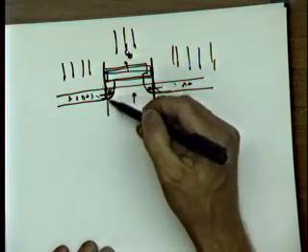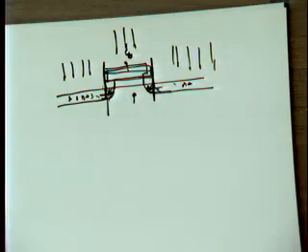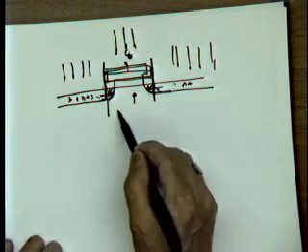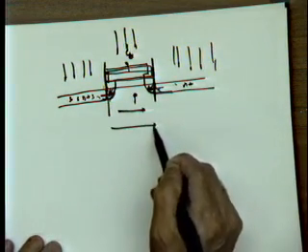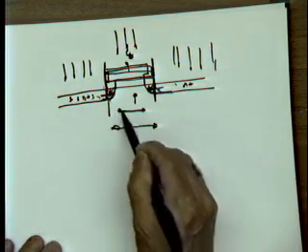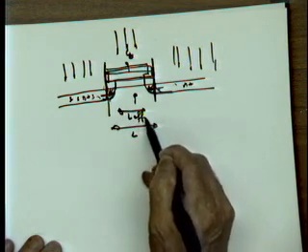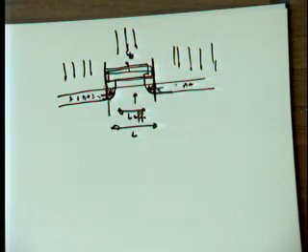This overlap region is totally worthless. Right? From a transistor perspective, it doesn't do any good for us. It destroys the channel. It removes the channel. So now instead of having an L, which is initially this big, we end up with an L which is equal to L effective, which is smaller. The actual channel length is going to be smaller because of this under diffusion.